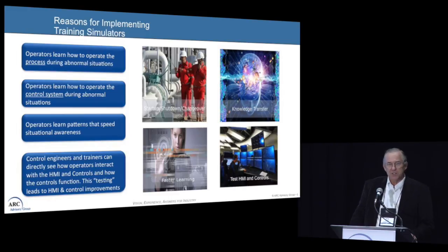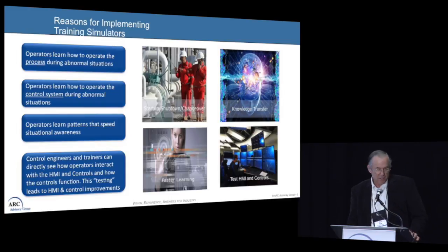You find errors in the displays, and some of them are kind of preference issues. Especially when you involve the operators with the construction of those displays and give them the capability of criticizing and modifying the displays, they will often come up with some very good suggestions on navigation, presentation order, sometimes coloration, blinking, all of the other characteristics in graphic displays that are in use today.